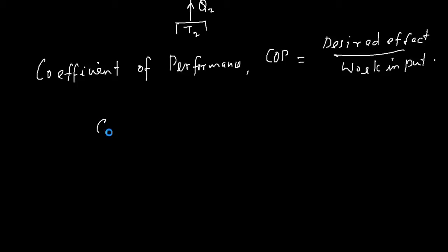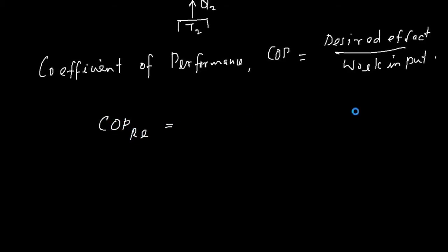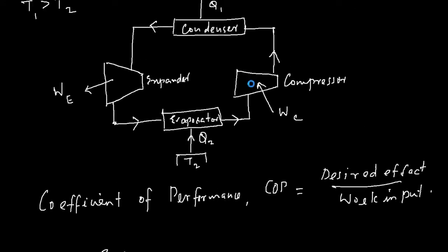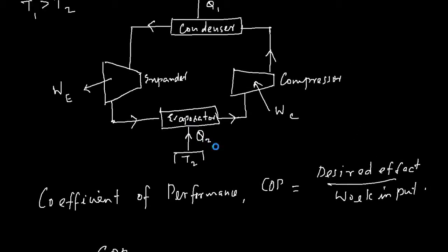So for the COP of a refrigerator, you can see Q2 is the desired effect, and because it's a reversible engine, the work transfer will be equal to the heat transfer based on the first law.